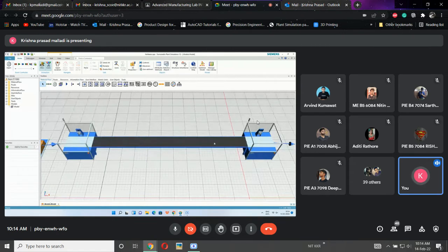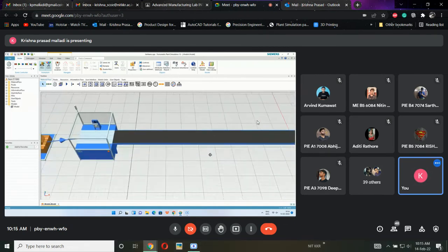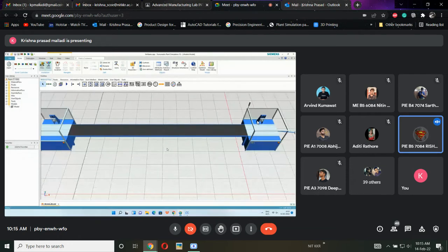We will say this is a belt conveyor. If this application is smoother material, then we can use this belt conveyor. If I am using some components which are at 100 degrees of temperature or have very sharp edges, what will happen to this belt conveyor? It will be damaged. It will be damaged.